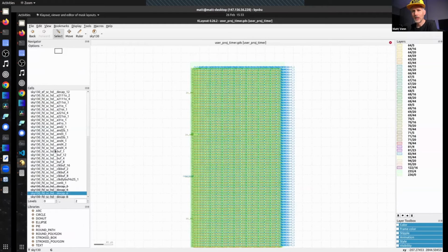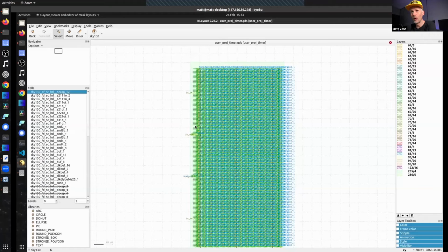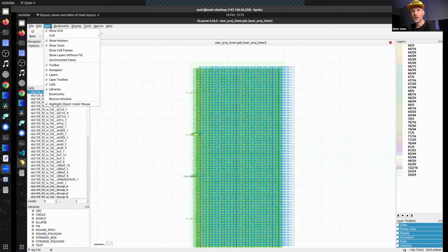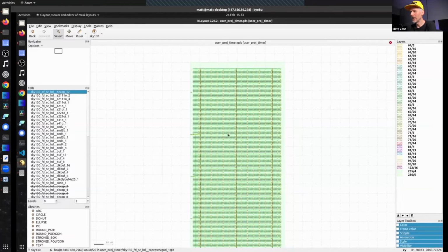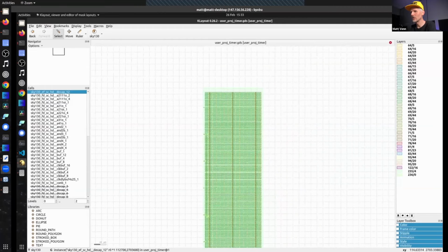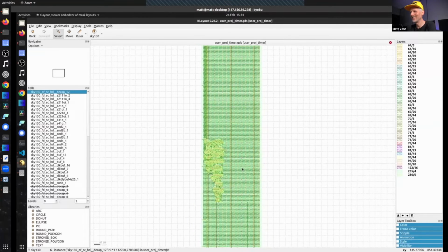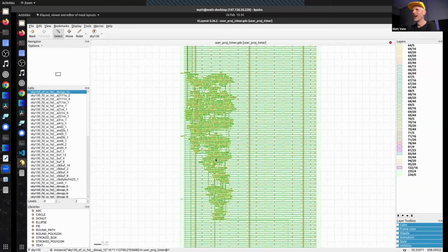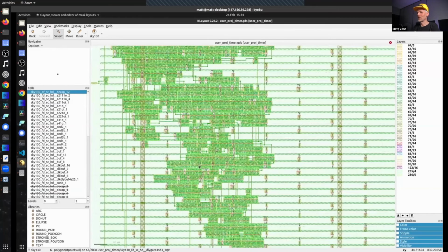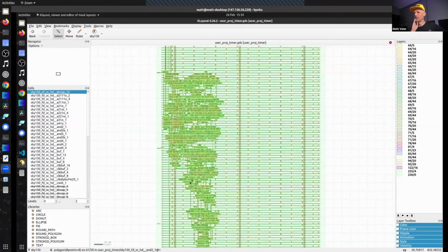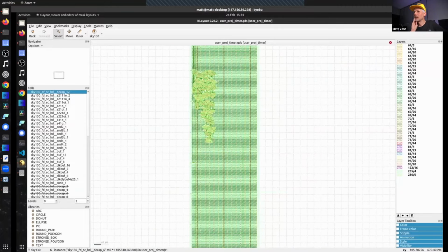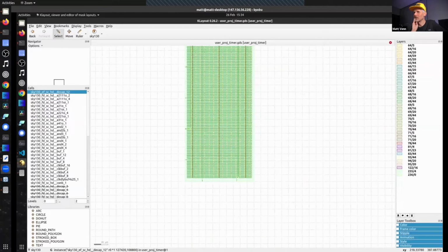Okay, and what I'm doing in Klayout here is turning on and off some of the decap cells and turning off the text, so you can more easily see how empty this design is. Really, there's just these standard cells at the bottom. There we go. And one reason for doing it like this is because it makes the timing easier, because OpenLane can do all the timing calculation and the buffering to those pins, and then we just abut it right up against the pad frame.